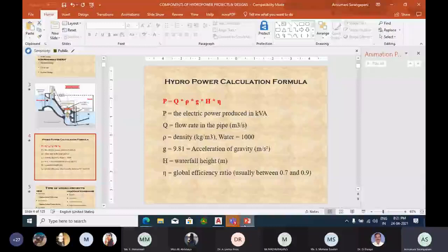Normally, I made 2 or 3 powerhouses in Madhya Pradesh, near Bhopal. That's only for 500 kilowatts or so. But there also we require a 10 meter head. Obviously, if we have a 10 meter head, then we can do it. But if I construct a check dam 10 meters high, my upstream people know that the water will be raised there and they will be affected. My catchment area will be submerged there. That's the problem. Thank you, sir.